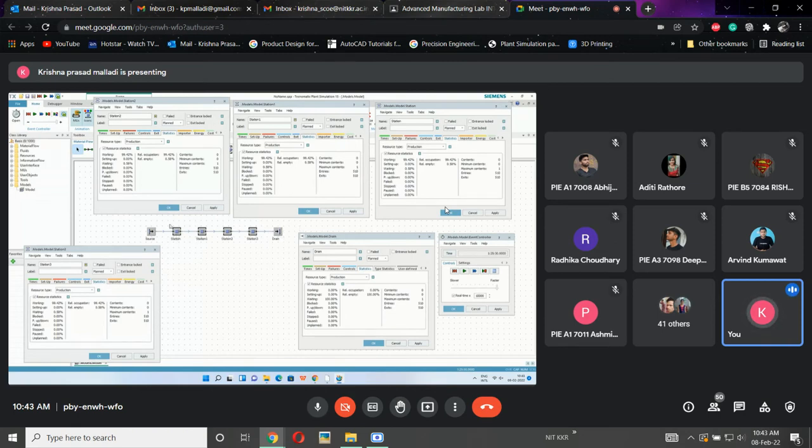That is why I have achieved only 356 parts here. Here there is already a work-in-progress part here, there is already a part here. That is why at the end of an hour, in the previous model, there are 356 parts I have produced, whereas 4 parts are still with the machines. Those account for the 10 seconds. That is why there is that delay. I mean 10 seconds of delay.